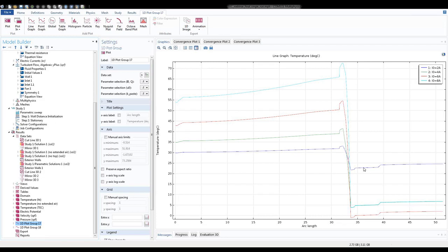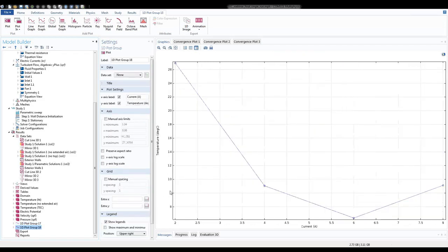I'd like to conclude my presentation with one more comment on the last graph, which is the volume average temperature in the diode emitter versus the injection current. We can see from this graph that this TEC system works for the specific diode laser at about a current of 2.2 amp here, assuming the operation temperature of this diode is 25 degrees C.